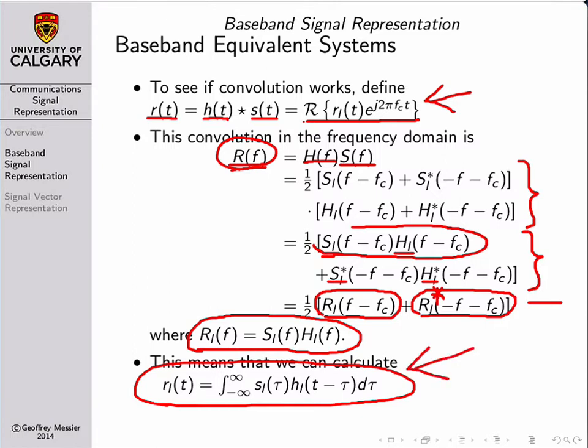And so really this last equation draws to a close our discussion of baseband signal representation. And again, just to summarize what we've done, we've shown that there is a mathematical relationship between a passband signal and the signal you get when you shift its frequency down to 0. And we've shown that that signal that's centered around 0 contains the amplitude and phase term of the passband signal. That is what carries the information in the passband signal, right? It doesn't carry the carrier frequency, but there's no information in the choice of carrier frequency.